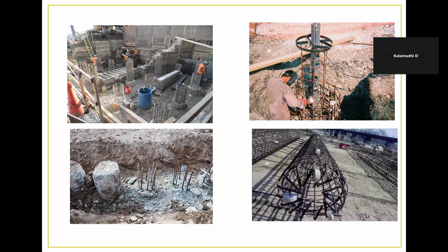What I mentioned here is micropile. A micropile is nothing but a steel casing filled with concrete, which is shown in this particular figure. When required and as the diameter of the micropile is increasing, the reinforcement cage also can be placed inside the pile to improve its structural capacity.